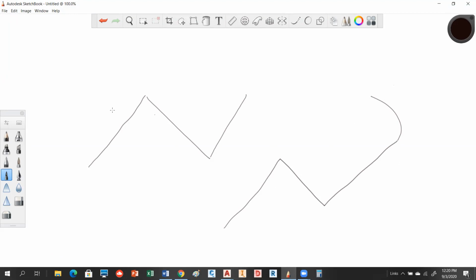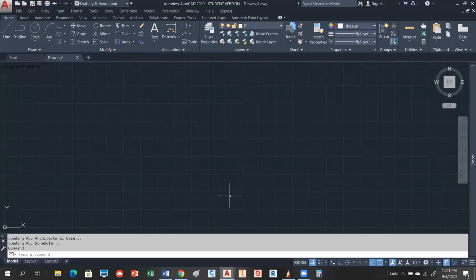With a line option, you have these guys here that are called endpoints. With P-lines, these are called vertexes. So what you have is what's called a vertex, and the vertex exists like here, and here, and here. And there's a direction associated with this polyline, so it knows whether it's going, say, either that way or this way. So it's a very complex kind of thing. We've actually taken a look at a command that is a polyline, and that would be the rectangle. Okay, so we talked about that last week.